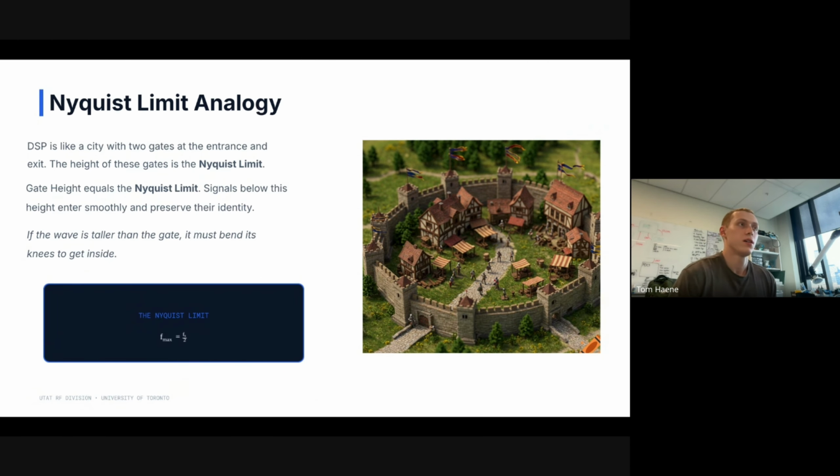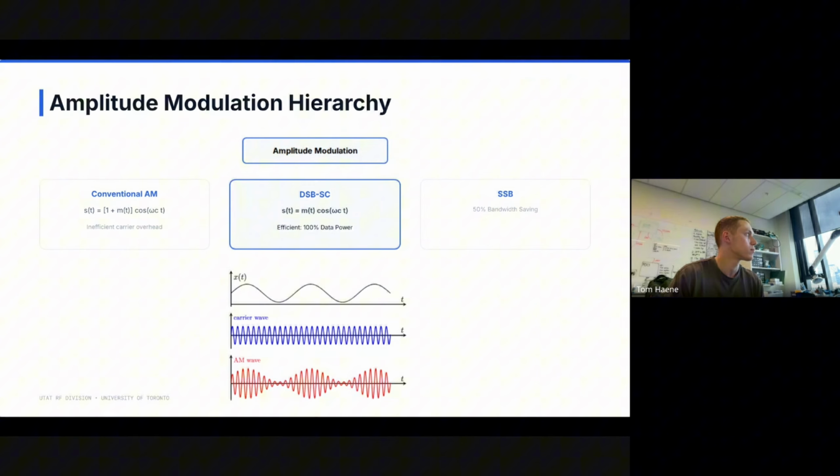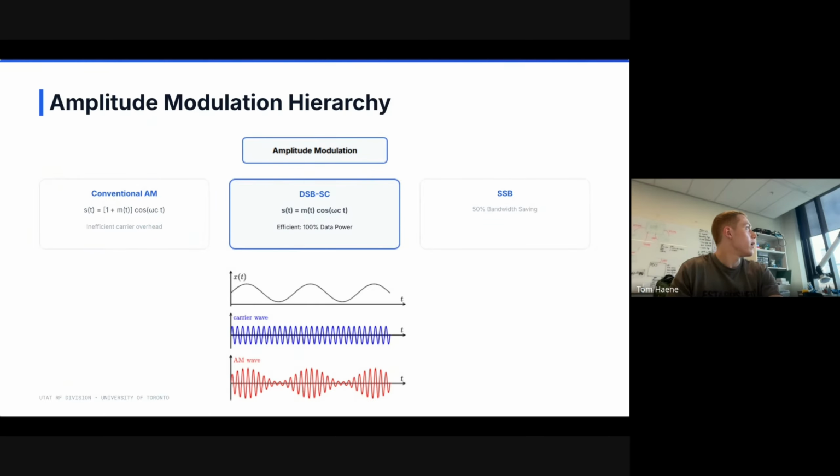Any more questions? So the modulation, you're multiplying the message signal and the carrier signal, right? What does that mean in hardware? What hardware is there? So you can do it in analog. There's an analog circuits class you can probably take at U of T that goes into details of how you make a multiplier block in analog hardware. It's a thing you can make, but the technical term for a multiplier is called a mixer.